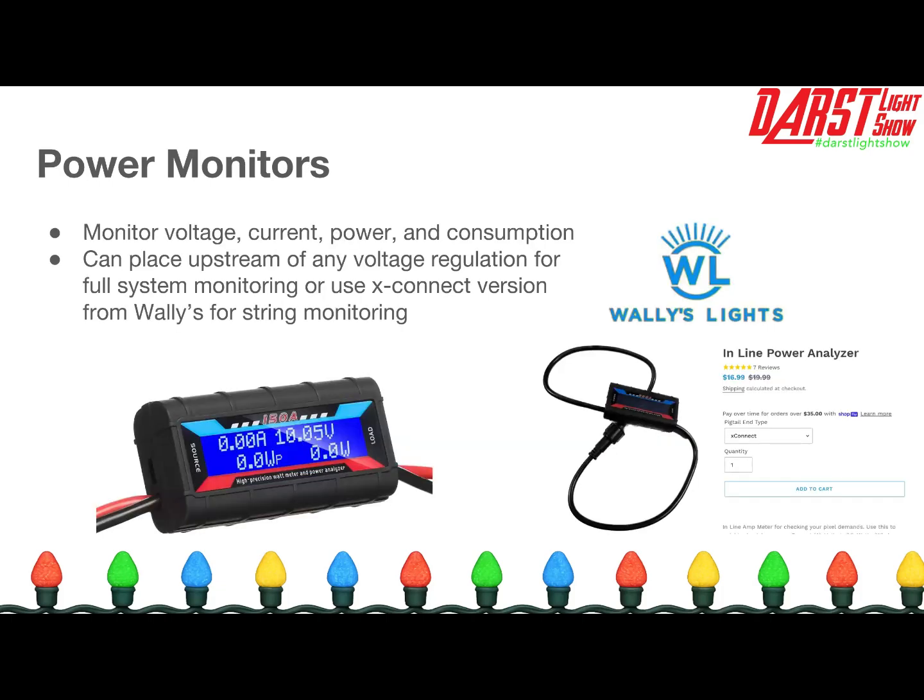So, speaking of power monitors, you can monitor with something like I show here. You can monitor voltage, current, power, and consumption. So you can get on Amazon and buy like the one I have here on the left. You might get it with SAE connectors already, or with bare wires, and you can hook this, say, upstream of a controller and see how much total that controller is using for its complete output. Or if you want to get more granular, Wally sells the same thing, but already pre-wired up with an X-Connect connector, and you can plug this into your string and see your actual power consumption.